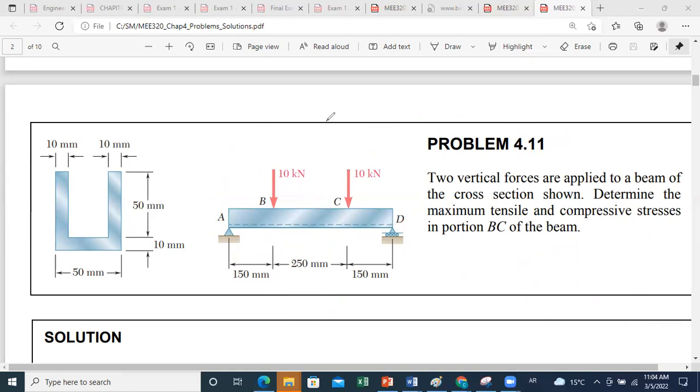Okay. And also in statics, you have learned how to determine the centroid of a certain part. Here you have several possibilities in order to determine the centroid location. You can divide your parts, and the first way is to consider that this is a rectangle, rectangle 1. This is rectangle 2. This is rectangle 3. So I divided my area into 3 areas, 1, 2, and 3.